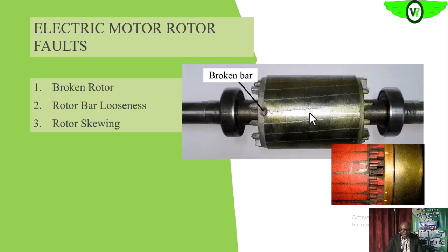Another thing that can affect it is when the bars are loose within the slot. These are the bars. If they are loose within the slot, maybe because of poor handling and what have you, that will also affect the efficiency of the electric motor.